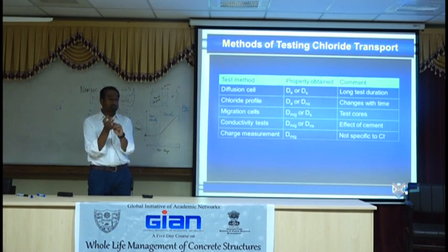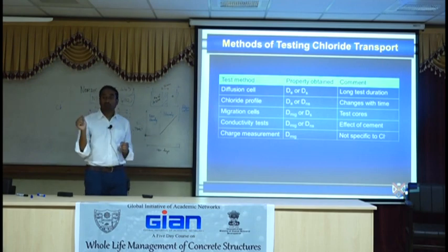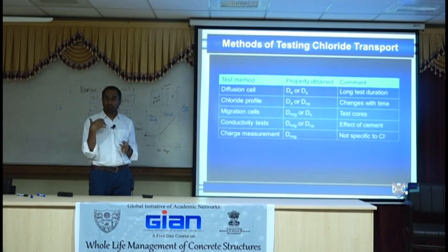One for silver nitrate spray. So silver nitrate spray is a good thing for site work as well. You can take a core or you can drill a hole into site for collection, then you can spray silver nitrate afterwards to see how far the chlorides have gone in.